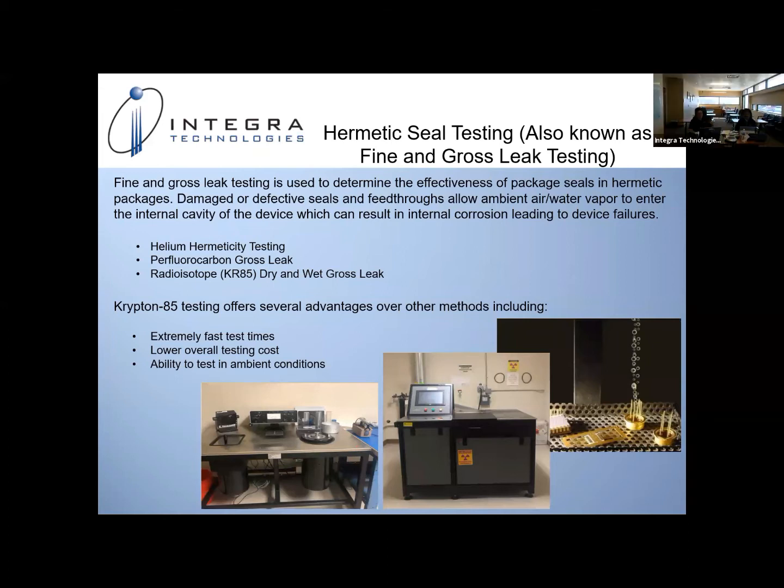Okay. So XRF externally, leads, lids, package material. Internally, we prefer to do EDS. You're looking at things such as the die attaches, the bond wires. You can look at bond pads. So XRF externally, EDS internally is our preference.